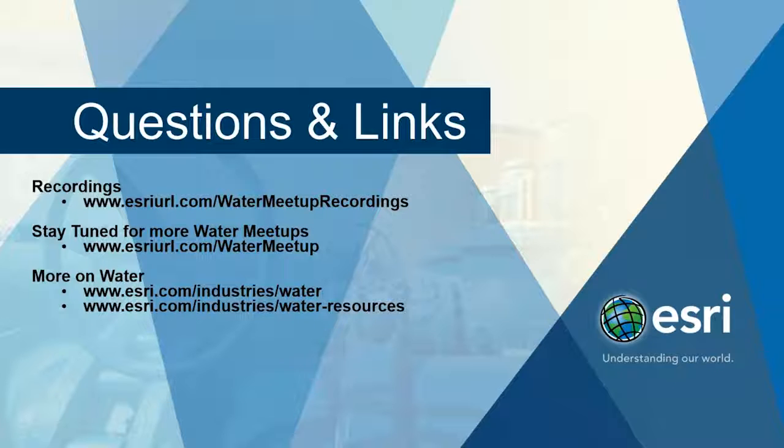But I've had a couple questions now about actually locating the buried asset using GIS, using a high accuracy GPS receiver to mark your locates for an OOPS call. So I'm not sure if that's the direction they're going. We don't do that. We go off our as-builts, but the 2 people that have asked me this question have had mapping that was surveyed by surveyors. So they know that that asset is dead on.